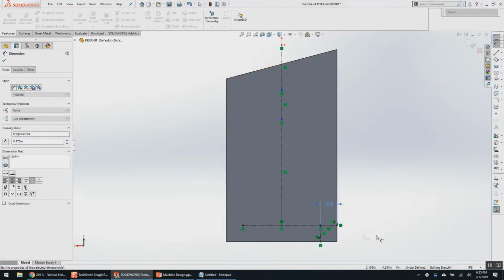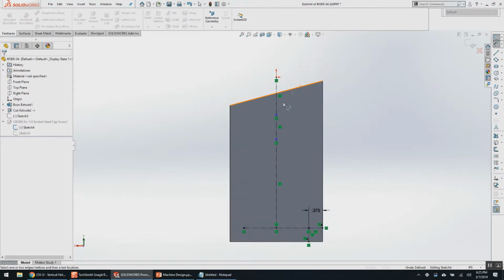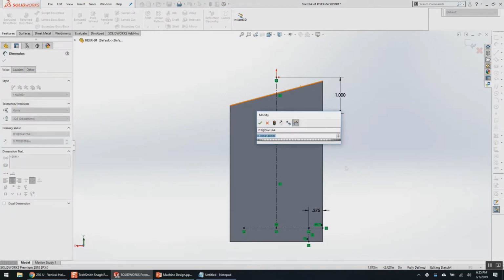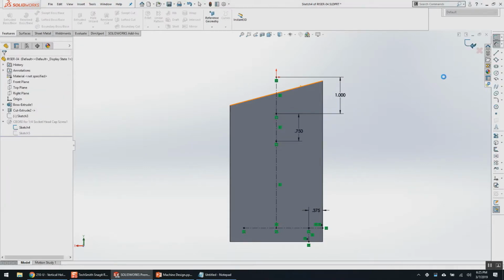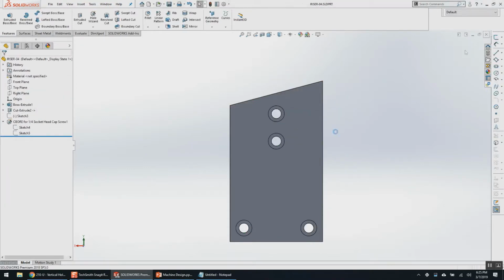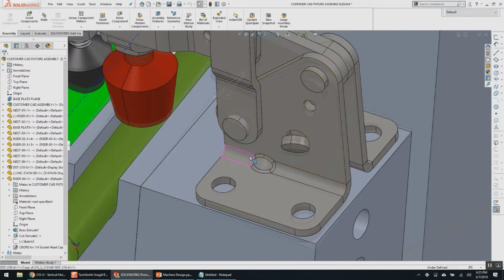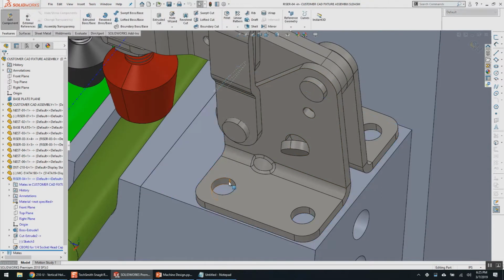So in this instance, I say I want them 3/8 away from the edge, and these first holes are 1 inch. I'm just typing a nominal, right? It doesn't matter at this point. 3/4, good enough. So I want a couple up top because that's where the leverage factor is going to try to be away, and then the couple down below just for stability.